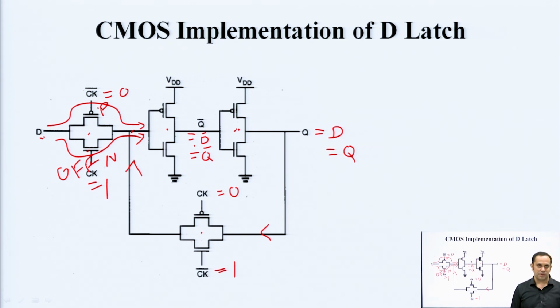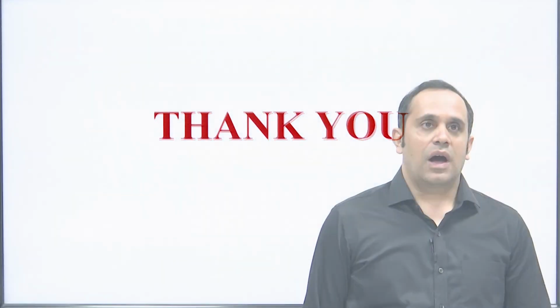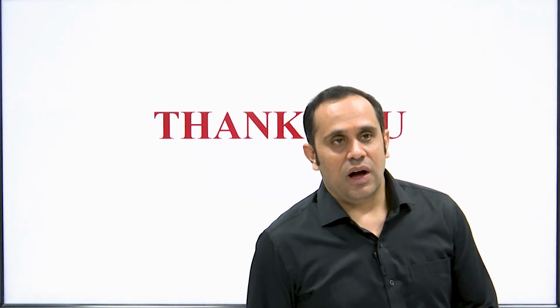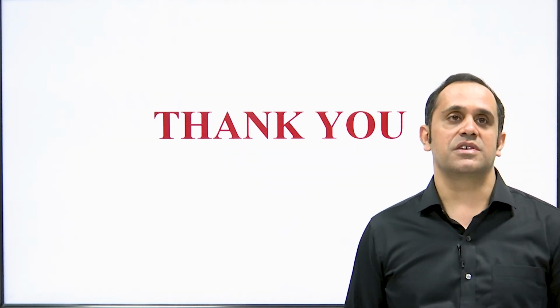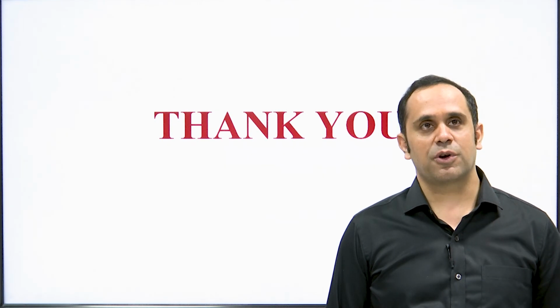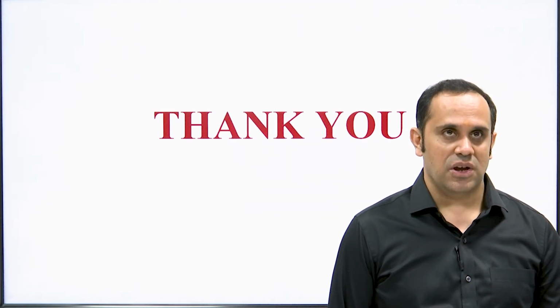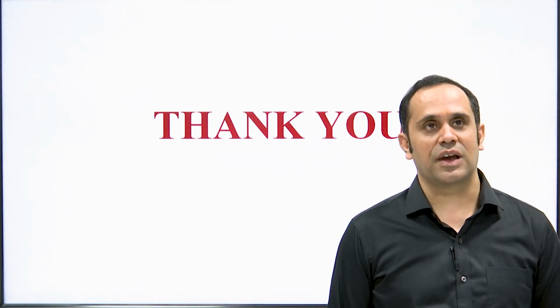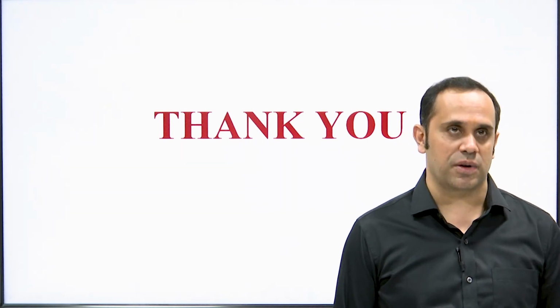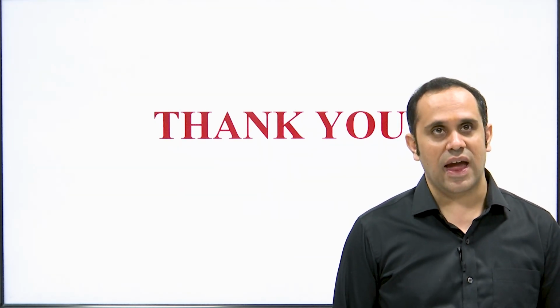So, with this I come to the end of this lecture. I have given you an implementation overview, how latching works, what is a bistable element, how data is latched, how memory can be implemented in a sequential circuit. We have done it from the point of view of a latch. Now, we need to move further in our following lectures and see how actually a flip flop works. So, with this I end today's lecture.